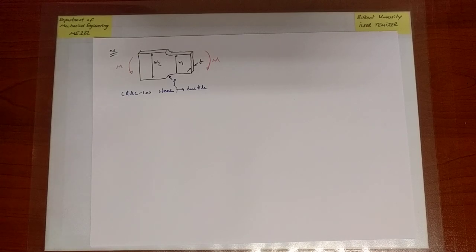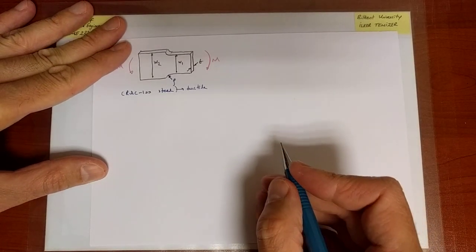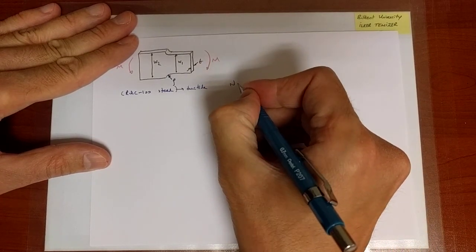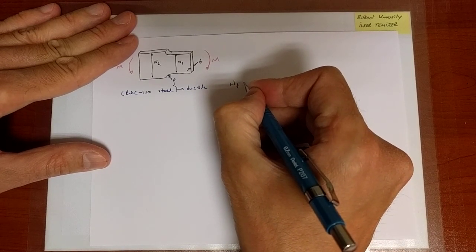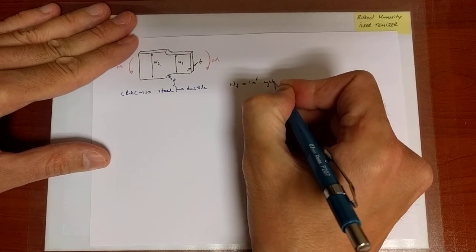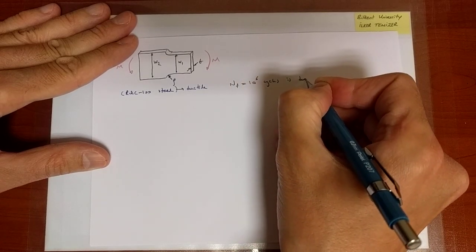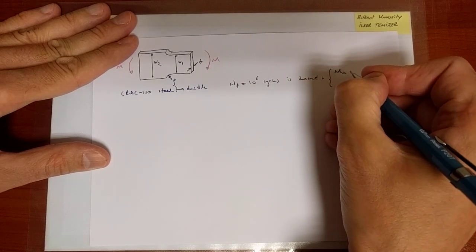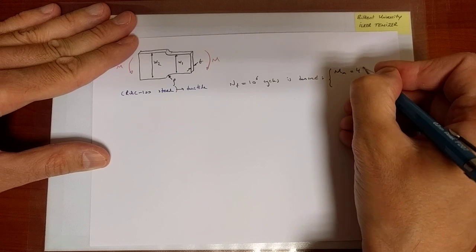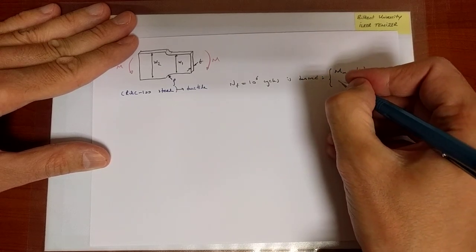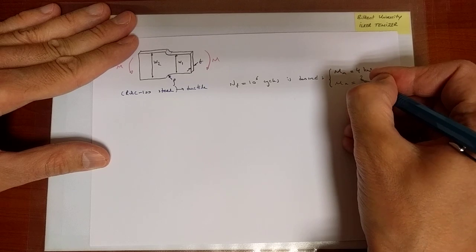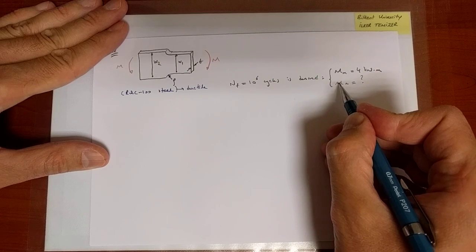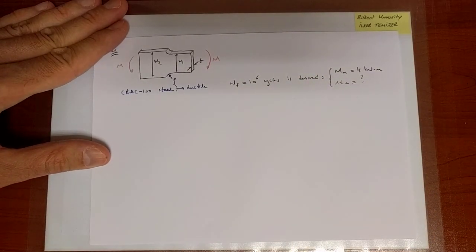So we are given the geometric parameters, which I will summarize in a second, but eventually what we desire is that we should be able to apply 1,000,000 cycles with a mean value of the bending moment at 4 kilonewton meters, and what we're trying to figure out is the maximum value of the alternating portion of the bending moment such that we ensure this many cycles.